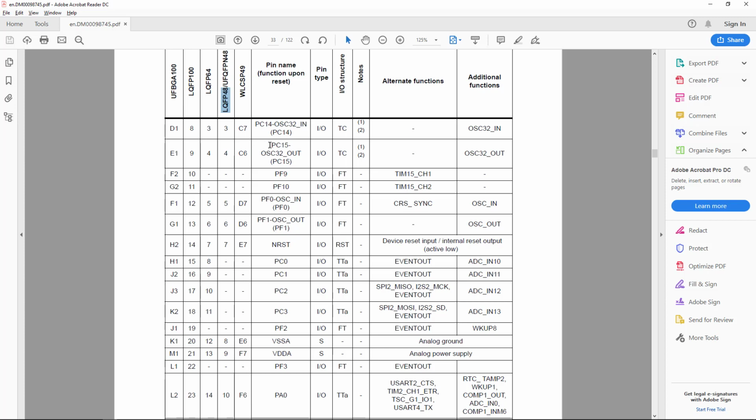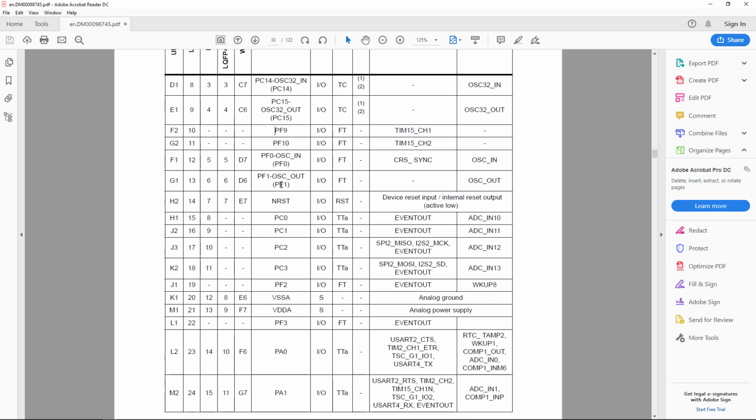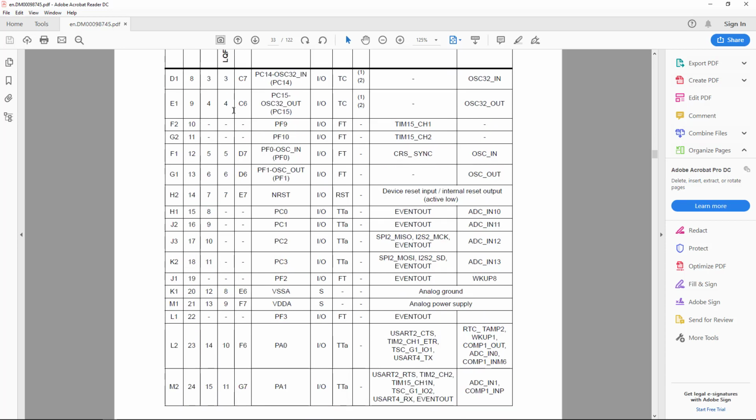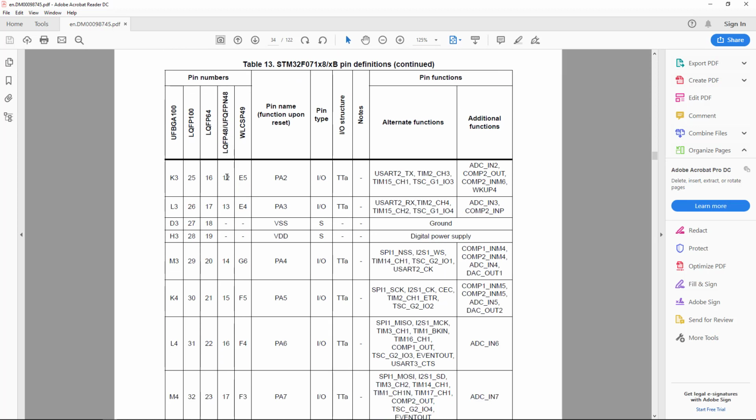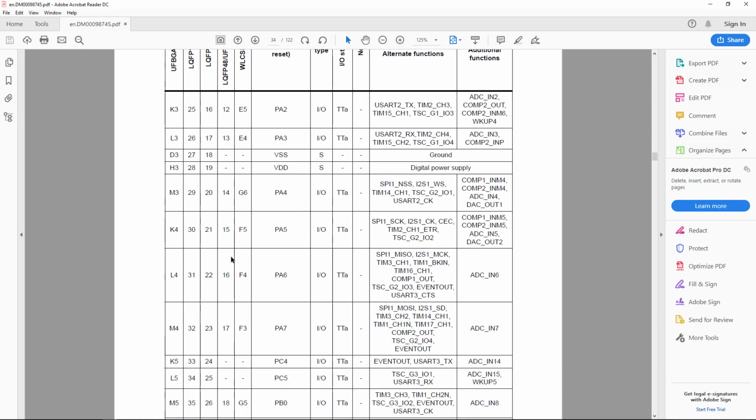Click on the Alt key on the keyboard. And now select while you are still holding the Alt key down. Okay, we don't care about these two in here. So let's take a look at pins. It's under LQFP 48. Okay, let's take a look at these. So 14, 15, 16, 17. Hold Alt down, select. Now you have selected 4 pins. Copy.